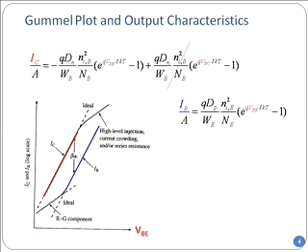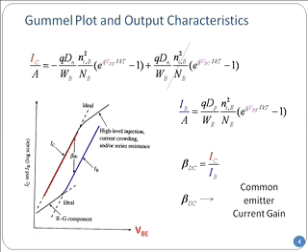So what I want, and I haven't done that yet, is to make sure that I_B is orders of magnitude less than I_C. And the ratio would be my current gain, how much amplification do I get as a result of this transistor action. And this we'll call beta.